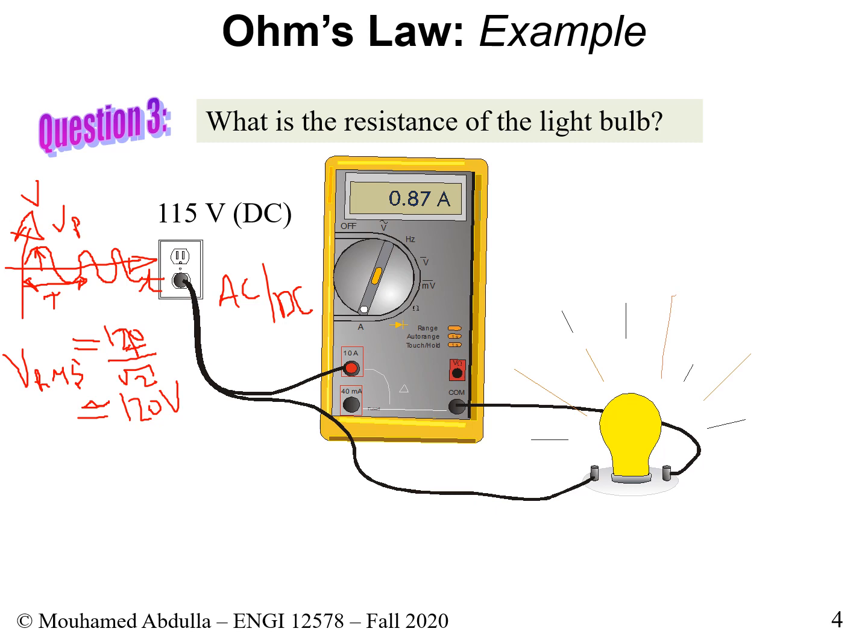Let's just assume it's just a battery. We have a battery of 115 volts. So this is the voltage that we have. Because there's nothing else connected here, we assume that this DMM, this digital multimeter, has negligible resistance. Then the entire voltage is really dropped here. So this entire 115 volts is what you get here. There's a plus, there's a minus. You will get 115 volts across this light bulb.